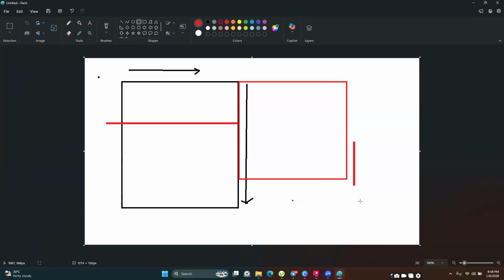That's why we were insisting that as you model the slabs, you model them in a very regular pattern. You start from left to right, then you go downwards, or in a clockwise manner. Just to reiterate, we've said the first direction for modeling your slab was your X-axis, and going downwards was your Y-axis, and that will come into play when we get to read the results from the slab.